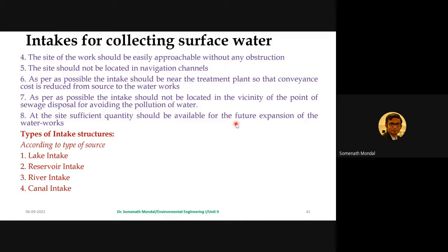Even if you choose a particular water body, in the vicinity of it there might be several points where you will get the most purified water, and there will be several points where you will get highly polluted or highly contaminated water. That part should be observed critically before planning a particular site for construction of the intake structures.